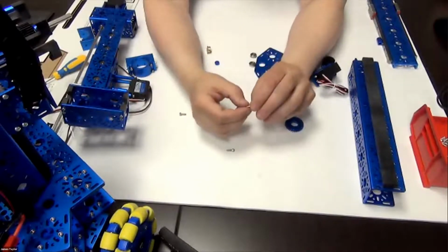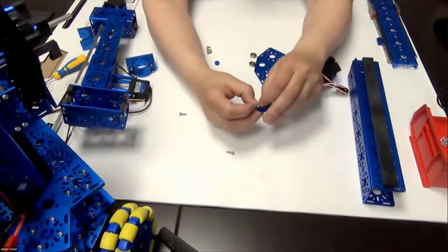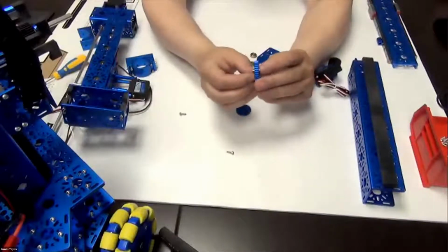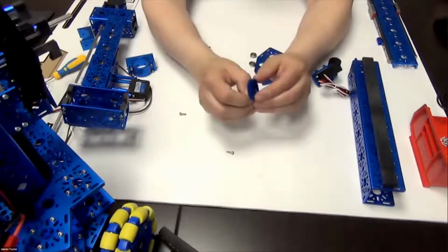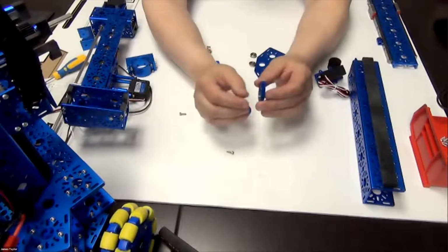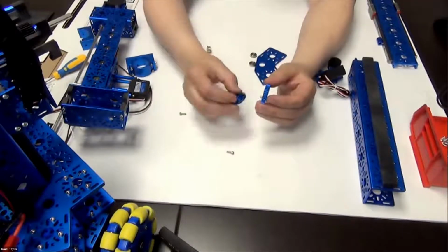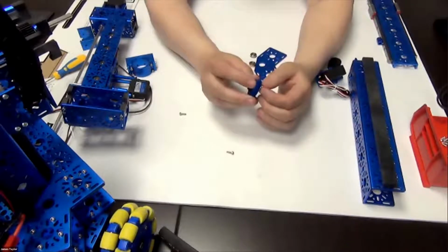Button heads are the small ones, so we gain a little bit of space and clearance. Because remember, these are going to be moving. They're rounded off, so if they bump into anything because they shift a little bit, you won't run into that friction of them touching. So that's what we use through the through holes to mount those in.